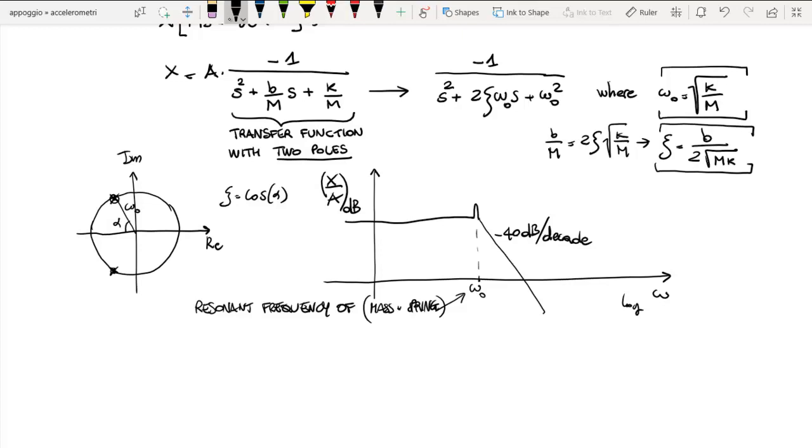Just to anticipate something that I will tell you later. Basically, if we want to measure the acceleration along 3 directions, we need, as you can imagine, 3 different springs: one that is measuring the acceleration, one that is allowing to translate the acceleration along one direction into a displacement along one direction, and the other two which are doing the same for the other two directions.